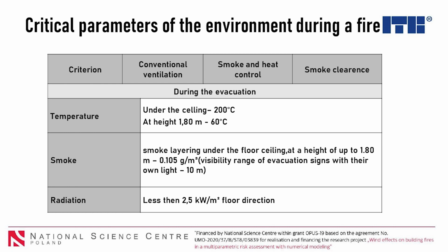And of course, another question is access to the fire source. Some kinds of ventilation systems, or a situation with the wind direction, can lead to a situation where the smoke layer is fully controlled, so fire brigades can easily have access to the fire. But first of all, to calculate the required time and the available time, we have to make some kind of analysis of the evacuation time. So we have two ways. One way is an analytical one for some simple cases, and the second way is to make a numerical calculation, as you can see here.